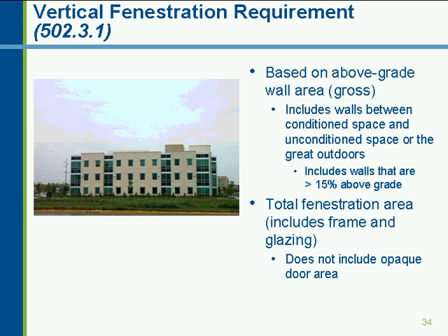If we have a big box store, for example, that might be down less than 10% of the window-wall ratio or glass-to-wall area ratio. So this is the one calculation you do need to do to determine how much glass you actually have in that building, and can you use Chapter 5 of the IECC, or do you need to go into the ASHRAE Standard 90.1 2007, or do you need to use the system performance approach?